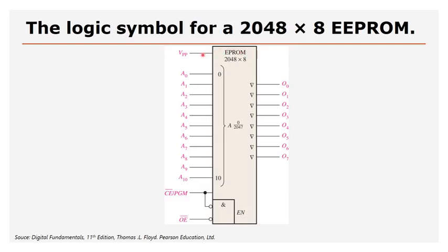So generally, once you connect an EEPROM into a circuit, it's already programmed. This is why you've got a program pin here, which replaces the write pin, the WE or WR pin. That pin will be activated with a special programming device, which you have to use to program this EEPROM.